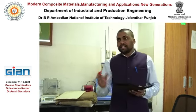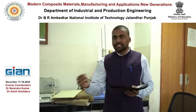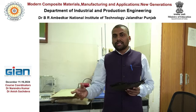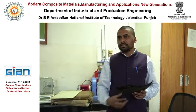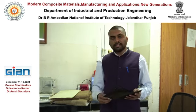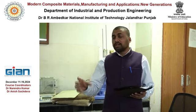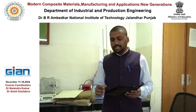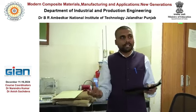So what happens is that if you look at the different composite manufacturing techniques, let's say it is hand layup or it is a compression molding technique, where you are curing at elevated temperature, so that your curing time is reduced and you can produce multiple components within small time. Or let's say vacuum bagging technique. Since the technique is different, the properties of composites are also different, right? And one of the reasons is the voids. Void is nothing but an air gap in the composite material, right?